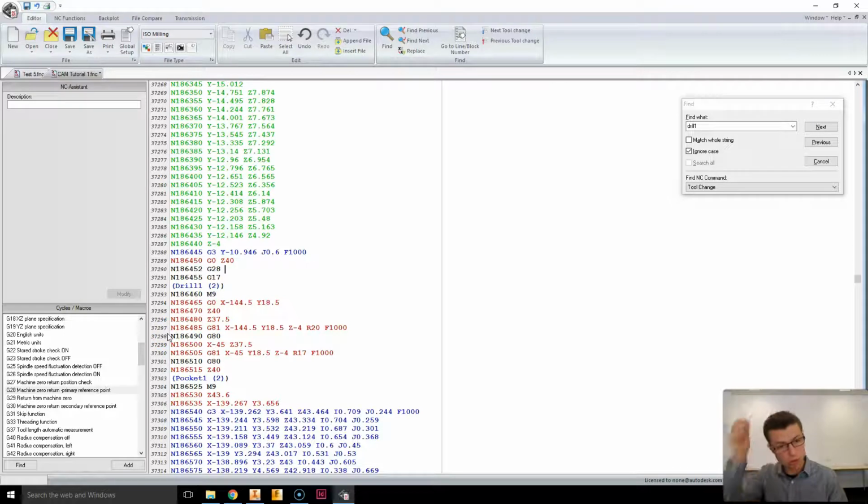Then going to customize it because we just want the Z to go up slightly. We're going to go up another 4 millimeters before it starts doing anything else, and we want the A to turn into a 180 rotation. So we're typing in the A axis 180. This is basically the bit that's quite critical.